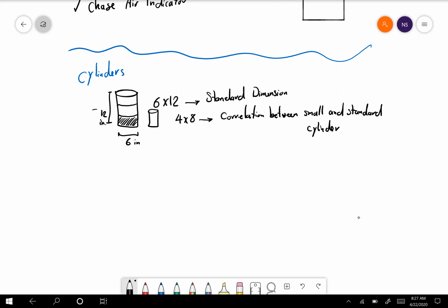You fill 1/3 of the cylinder, and you rod it 25 times to make sure that no air clumps are forming in the concrete, and you're distributing the concrete all over the cylinder evenly, right?